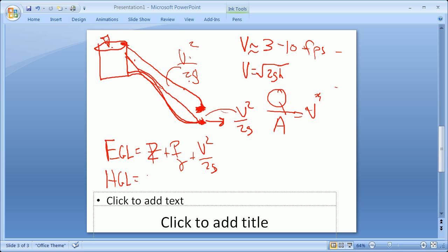The hydraulic grade line is equal to Z plus P over gamma. It graphs the piezometric level. And then what you'll see is at any one point in the pipe, the difference between the hydraulic grade line and the pipe is actually measuring the pressure. Remember that pressure is energy per volume, and unit weight is weight per volume. Therefore, when you get these, you end up with energy per weight, which in fact is what we know a pressure head is. All right, so that is the basics of pump curve stuff.